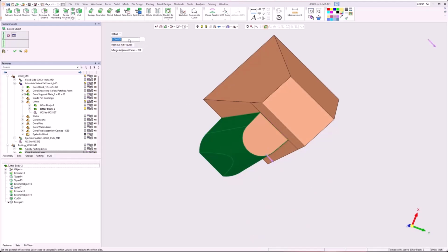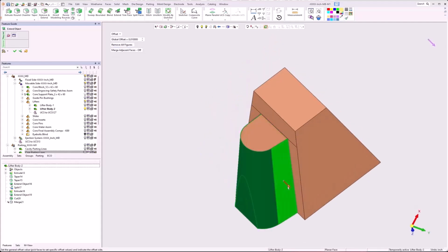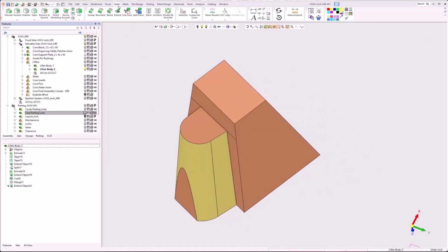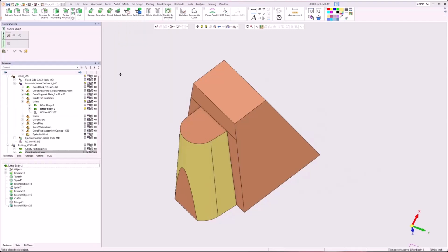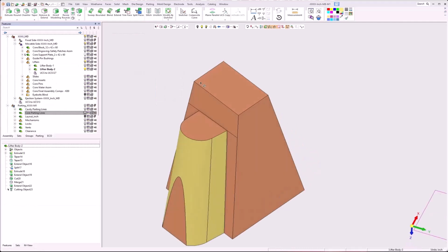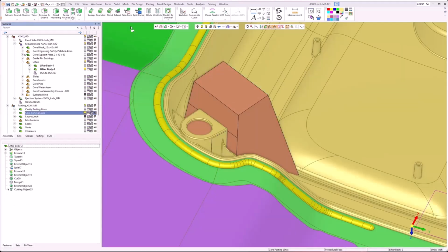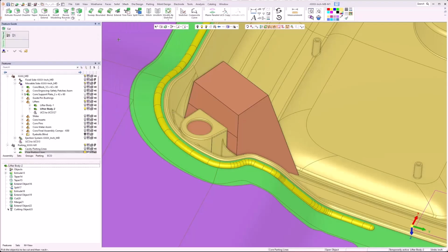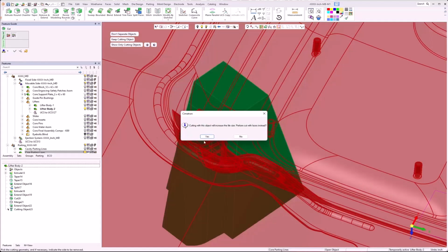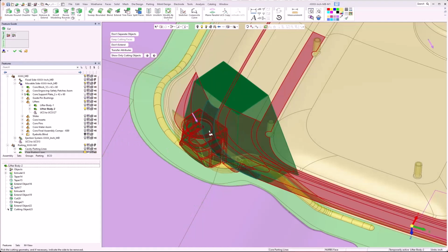Offset 10 thou, this time inboard. And now is the time that we can make the cut object. We can do a solid cut on this. And you notice we get the result without having to do anything with that top face.